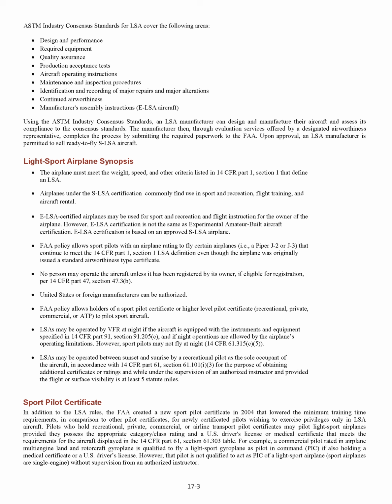LSAs may be operated by VFR at night if the aircraft is equipped with the instruments and equipment specified in 14 CFR Part 91, Section 91.205(c), and if night operations are allowed by the airplane's operating limitations. However, sport pilots may not fly at night, 14 CFR 61.315(c)(5).